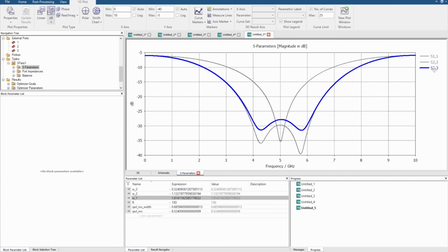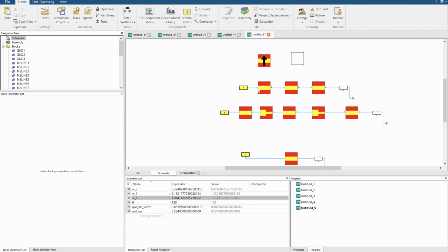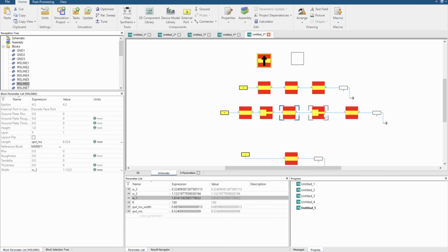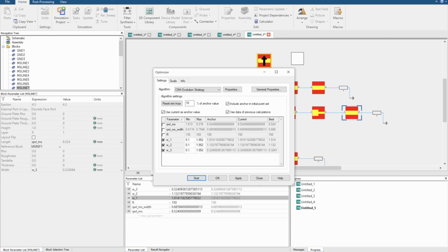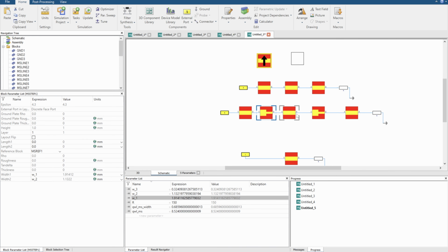However, there are reflections between each single step, and those reflections show a poor performance, although both of these systems perform very well. So rather than optimizing for this system, it's more wise to actually ask the optimizer to optimize for this network here. It doesn't have to control any more. For example, it's still controlling just 3 values. However, you've accounted for the S parameter losses between this microstrip step.